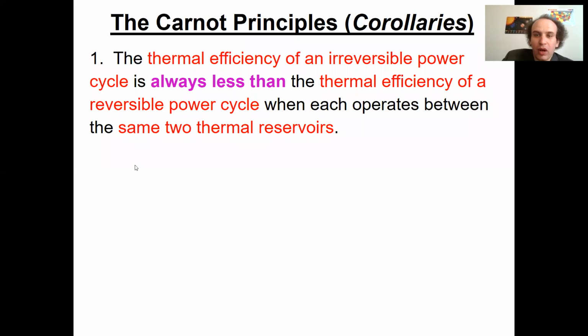So how do you measure it now? Do you agree? It can be, we will prove it, but even on a naive level, just mentally, semantically, you may feel that a reversible cycle is better than an irreversible one as long as they operate between the same two reservoirs. Do you agree? Right? Let's say I have the same reservoirs, I have temperature TH here, and I have temperature TL here. Let them be in Kelvin.